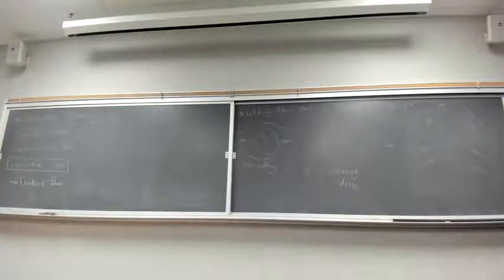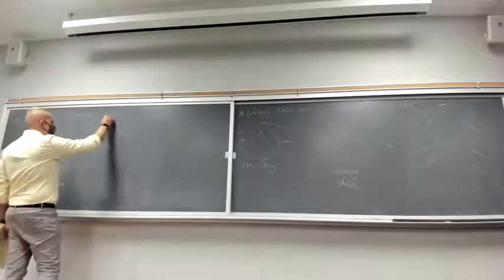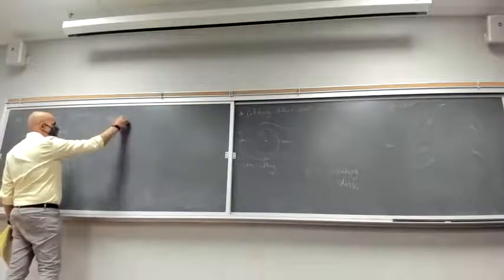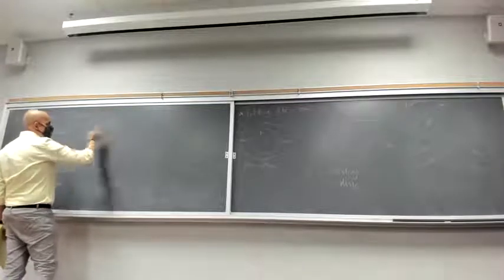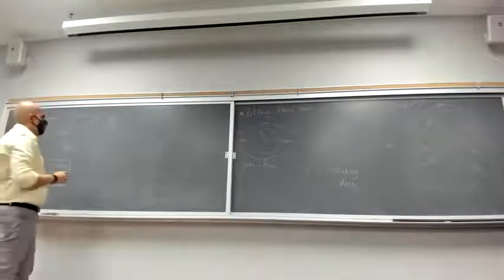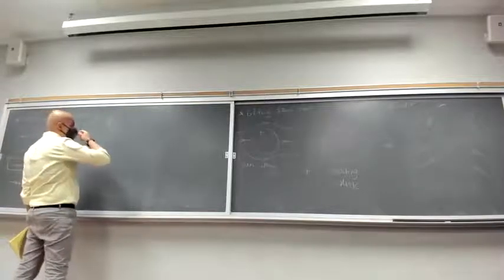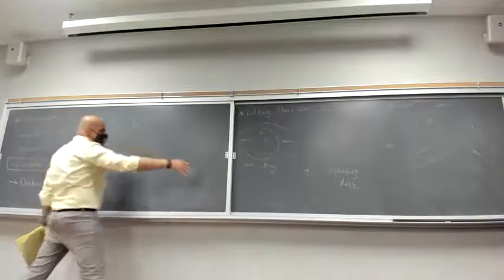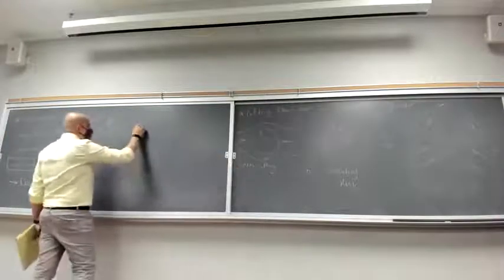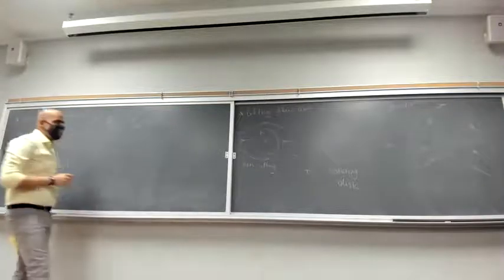So the stream function of this, which I'm going to call lifting flow over rotating disk, LR, is going to equal the stream function of the non-lifting flow, NL for example, plus your vortex flow.